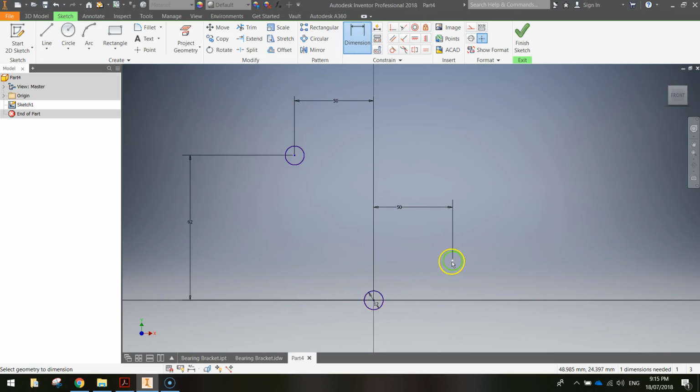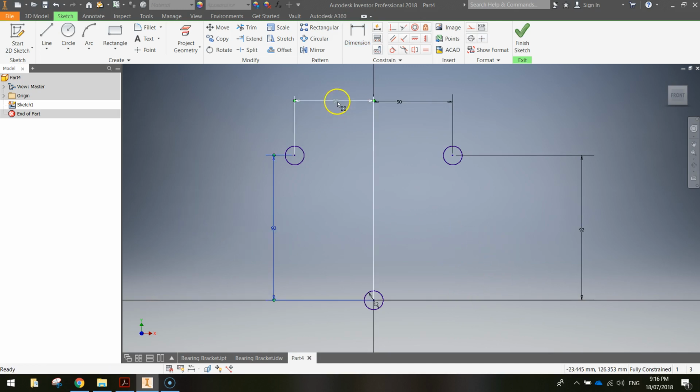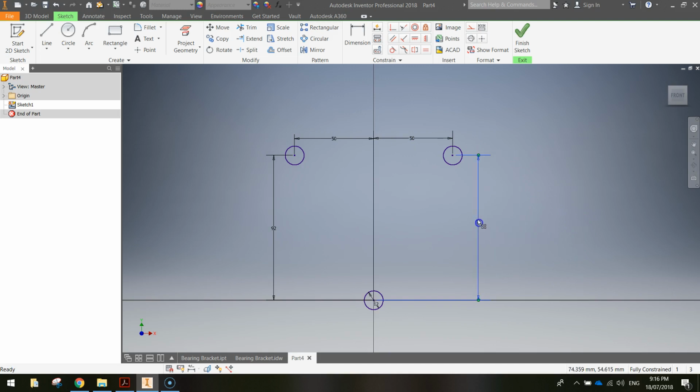We'll do the same for this circle on the right, so just click somewhere on the outside of that circle. Go and click on the origin and then come out to the right and we're going to type in 92 mil. Alright, press escape to turn that off, and I just want you to move those dimensions in a little bit closer to the circles so they're not so far away from each other. Something like that. Okay, so that's how your page should be looking. 3 12mm circles, all nicely dimensioned.